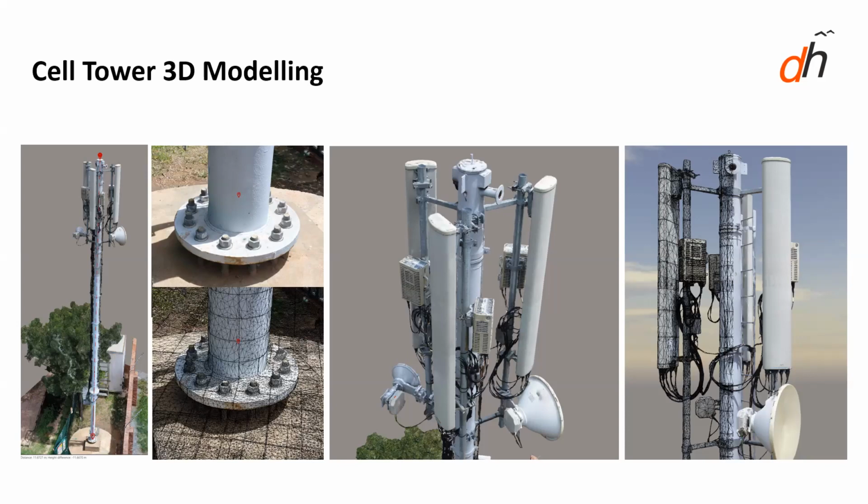And capturing data around cell towers is also a challenging task for various reasons, because of the small components that you have around the cell tower that if you want to model, you have to have very high resolution imagery of, as well as the fact that the cell towers often have, let's say, a texture that's not very favorable for modeling. So one really has to be very, very careful about what data one puts into the photogrammetry workflow.